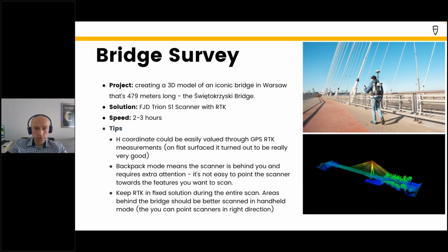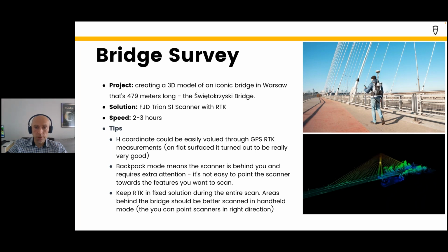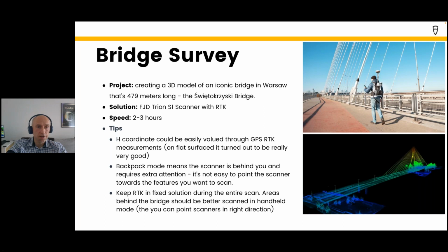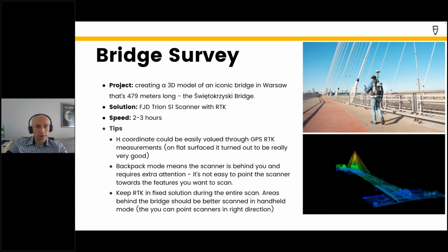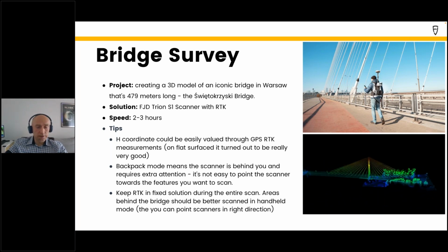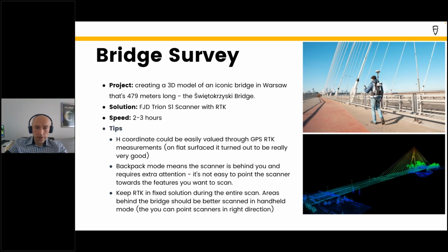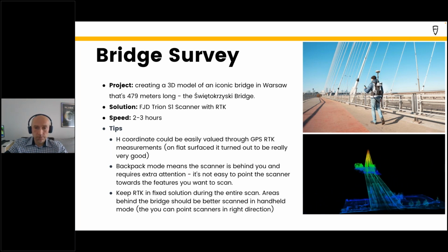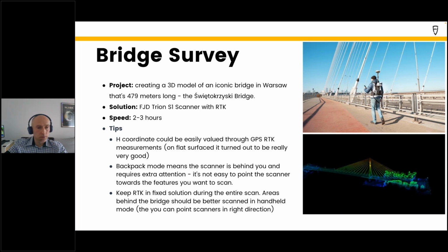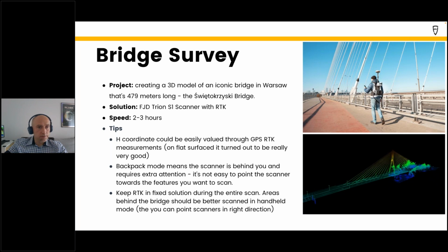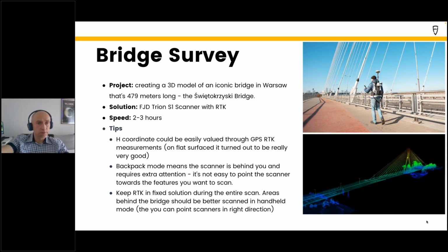Another small tip, try to scan early in the morning or at night, because cleaning the point cloud of people and cars is a nightmare. So to scan in the city, the best time is the night. And of course, you will get the best results when having a fixed solution all the time. Okay, that's all I need, I think.